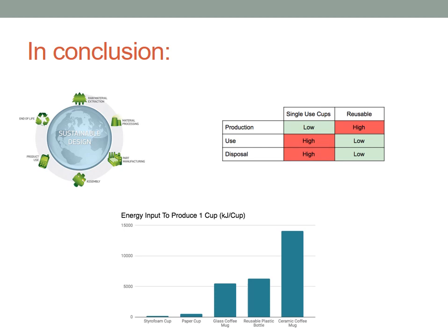And that is a really complicated concept. At face value, it looks quite simple, but as we drill more into the different decisions that we have to make, we'll find that very simple decisions, like using an adhesive instead of a screw to secure two parts together, have huge impacts for recycling at the end of life, because it's very hard to separate something that's been glued. But the main thing I'd like you to take from that point is that you need to have a good general understanding of these decisions and their impacts.